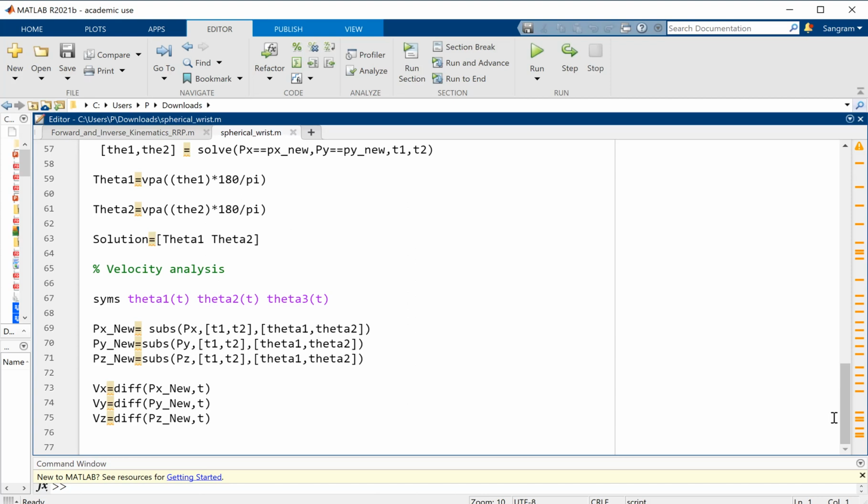When we performed the inverse kinematics, I did not specifically mention this, but it was only performed on positions. If you look at the way the inverse kinematics solution is computed, we gave MATLAB the values for Px, Py, and Pz, and we equated that to a symbolic expression that contains θ1, θ2, and θ3. And then MATLAB solved that expression and gave us the values of θ1, θ2, and θ3. Do you agree with me? This is what we did for inverse kinematics to find joint angles.